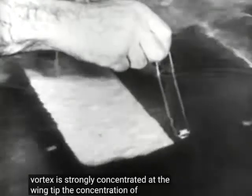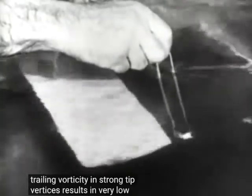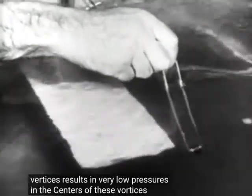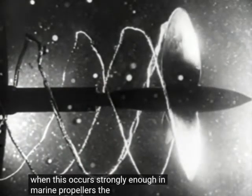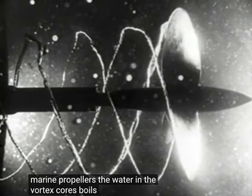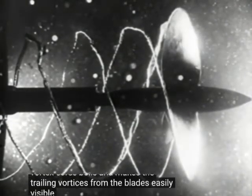The trailing vortex is strongly concentrated at the wing tip. The concentration of the trailing vorticity in strong tip vortices results in very low pressures in the centers of these vortices. When this occurs strongly enough in marine propellers, the water in the vortex cores boils and makes the trailing vortices from the blades easily visible.